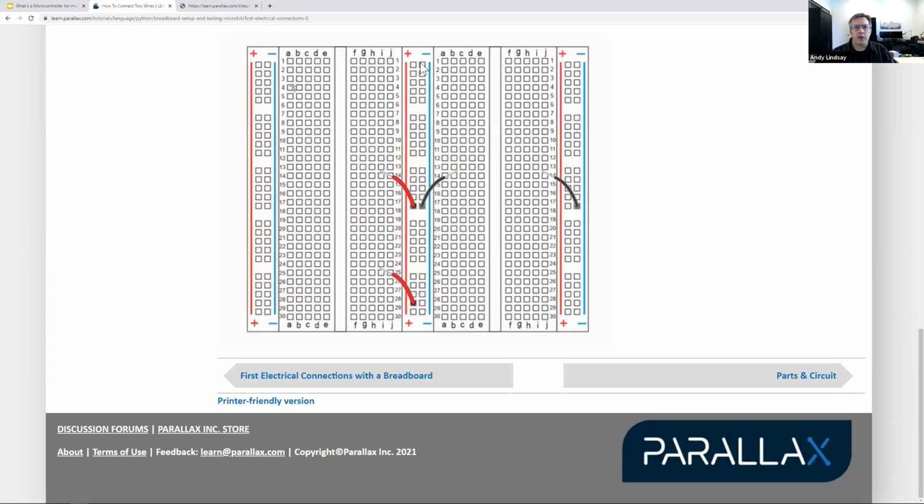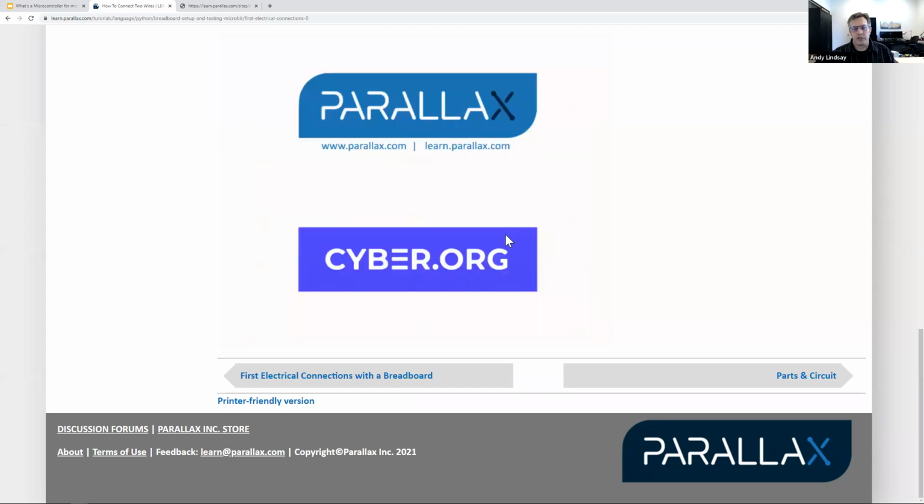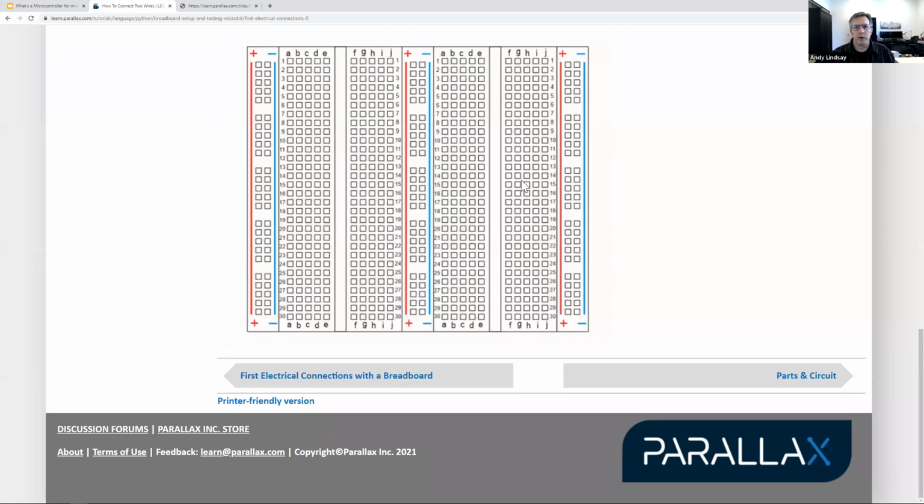And you can even run a jumper wire between 2 blue minus lines so that you can make a much larger connection that happens to be adjacent to all the rows that we're going to build circuits in, which means that if you need a common connection like 3 volts or the negative terminal of your battery supply, they're right next to any circuit you're building.